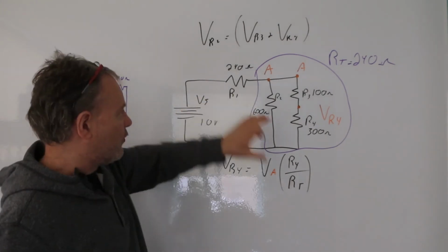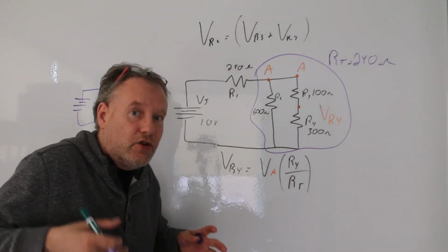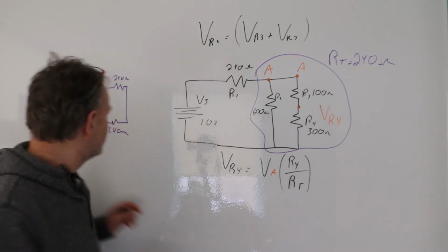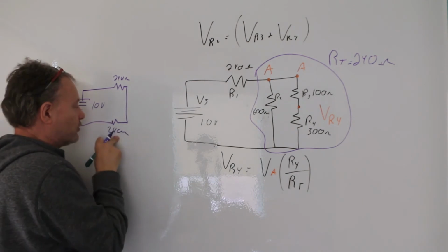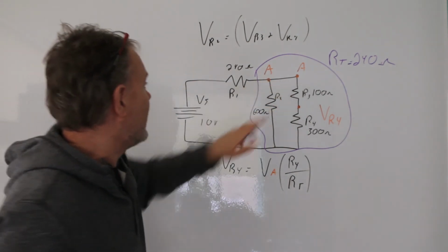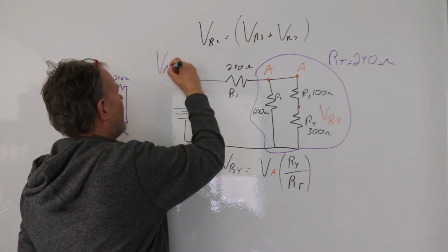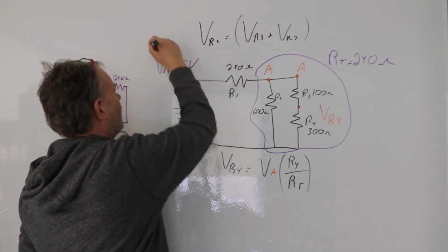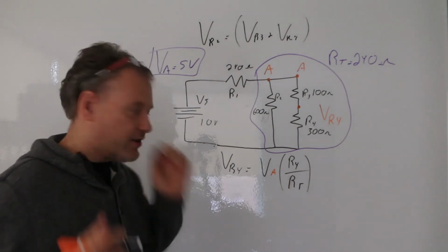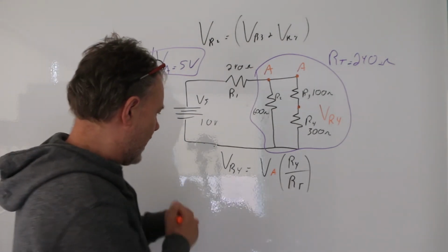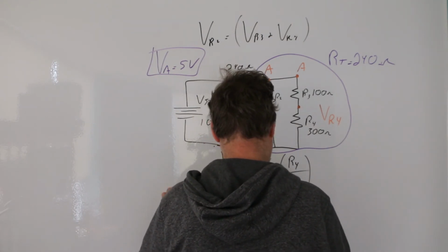And that's 240 and that's in series with another network of resistors whose total resistance is 240. So it's like 240, 240. So we know the voltage drop across that is 5 and we know the voltage drop across that is 5. So I can say then pretty simply and pretty securely that VA equals 5 volts. Okay, so I'll leave that there. So now let's actually go here and do this. So I'm going to put these values in here.